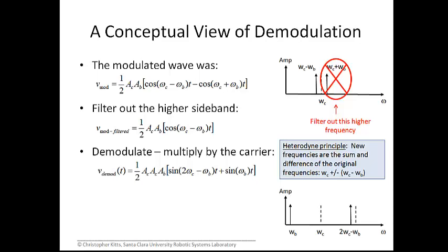In this case, demodulating. So they wind up being, if you look at the math, again, some amplitude out in front. And then I have two sinusoids. One is at the baseband frequency, and one is at twice the carrier minus the baseband. So it's gone even higher frequency. But most importantly, I have the baseband frequency back. That was my original frequency.